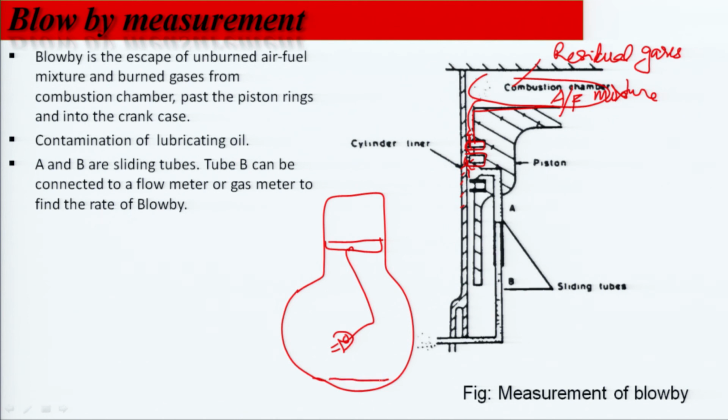There are some lubricating oils here. These are combustion products and the fresh charge also. So, the fresh charge as well as combustion products pass through this space and may get mixed with the lubricating oil at very high temperature. It damages the lubricating oil also; it contaminates the lubricating oil.